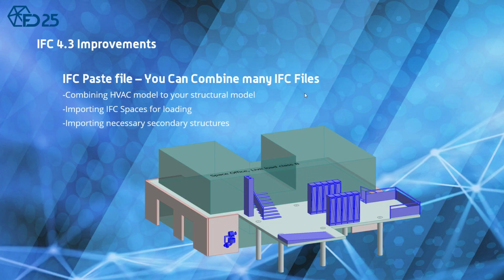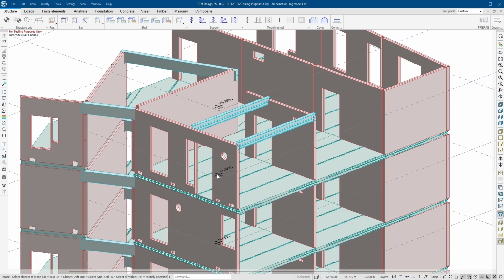An IFC-based file means that now you can combine many IFC files into a single analysis file. So for instance, if you have heating equipment or ventilation or a loading, like here we have an IFC space. So you want to import the loading data to your finite element model. You can import it later. The original IFC doesn't have to include it.